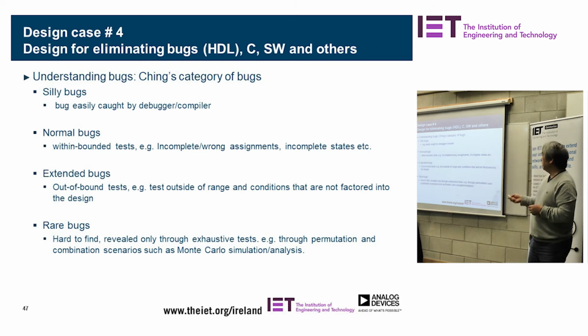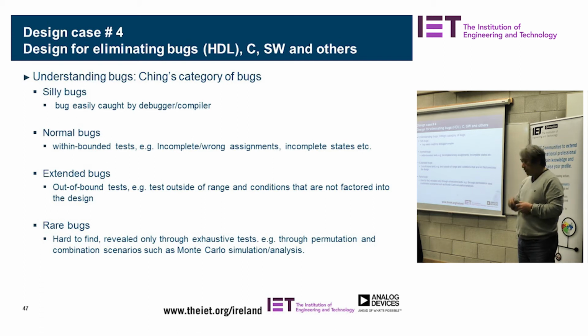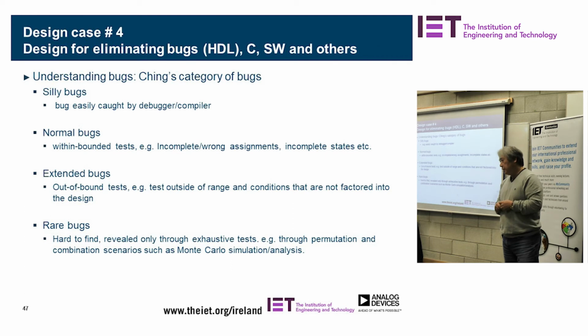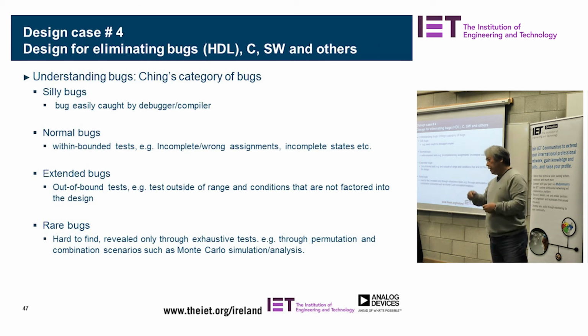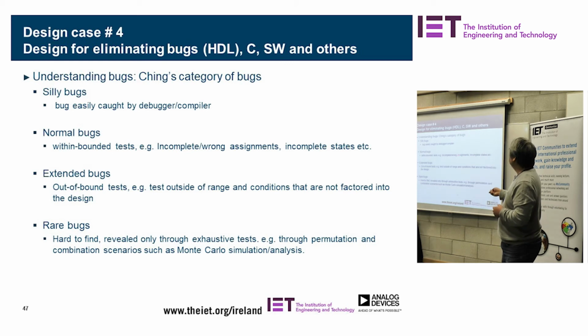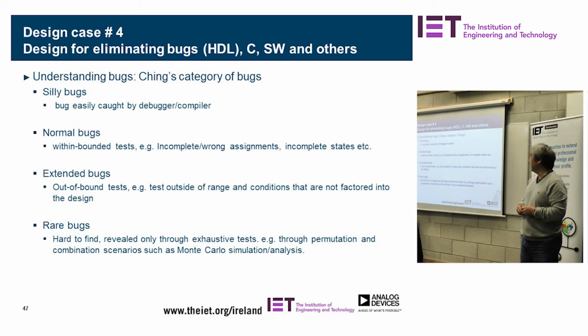Okay, so here's one of these cases that I actually tried to work on with a customer. A customer designed the I2C, and what happens is that they write to it, and then when they read it back, it resets itself, so the register disappears. Every time they read it, it disappears. So this actually falls in that bug category, incomplete assignments. So you still have people falling into that category.